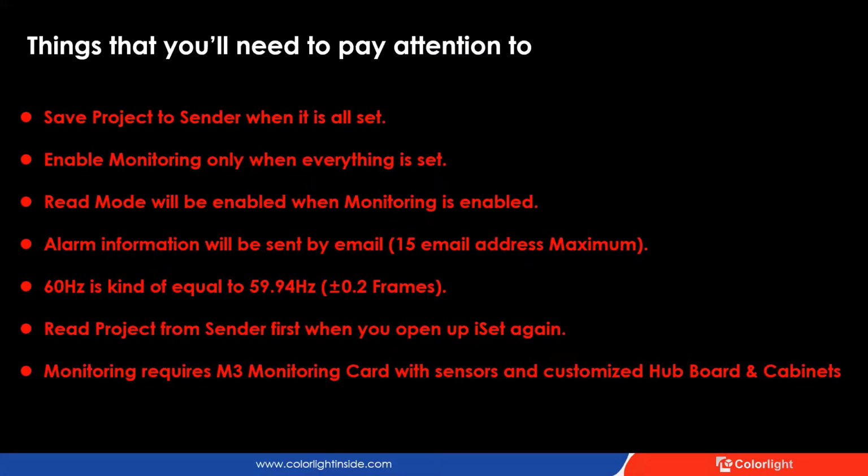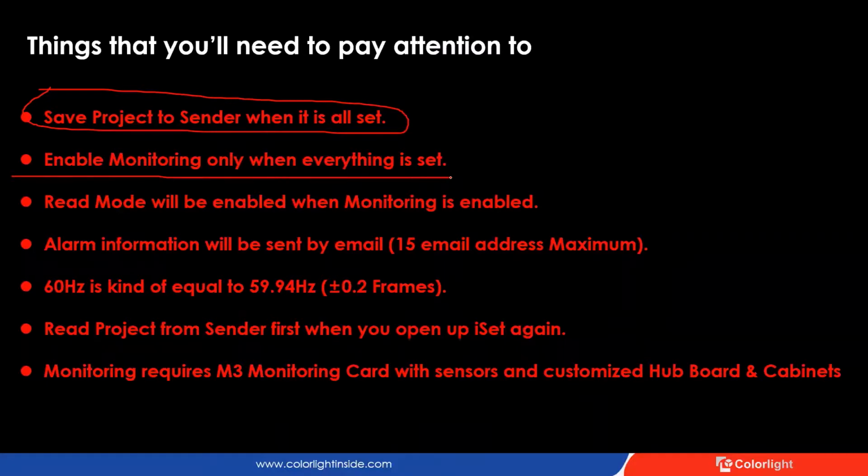Here I make the summaries of what you will need to pay attention to when you are using the monitoring features on iStat software. You need to save the project into Sender when it is all set, and you could enable the monitoring only when everything is set. So the monitoring is the last step that you will need to do. Make sure that you will not change the other settings here again, and then you enable the monitoring features. When the monitoring feature is enabled, the read-only mode will be enabled too.